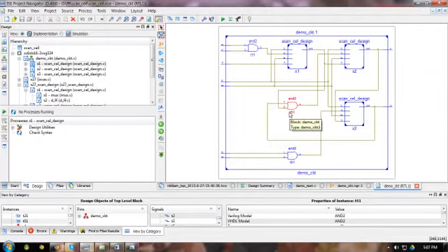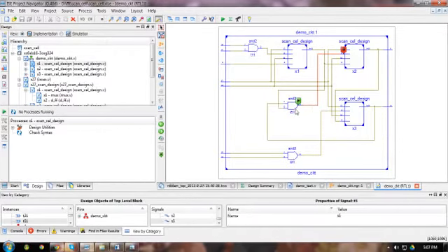So it means I don't have any controllability on this particular gate. I can't have any control on this gate, and it is internal to the design, and I cannot even observe the output of this particular gate, so I can say the observability is 0. So in such a case where I have a design where I want to test a gate or any logic which is present within the circuit, which is internal and which cannot be controlled by the primary inputs, then we go for sequential design.